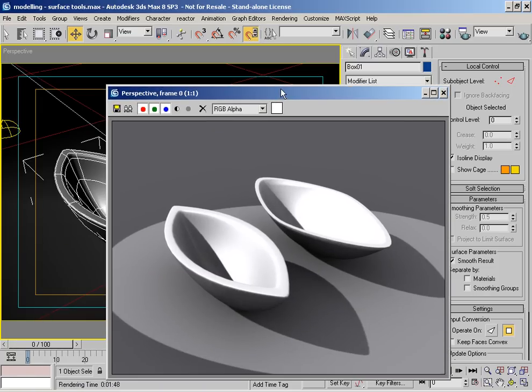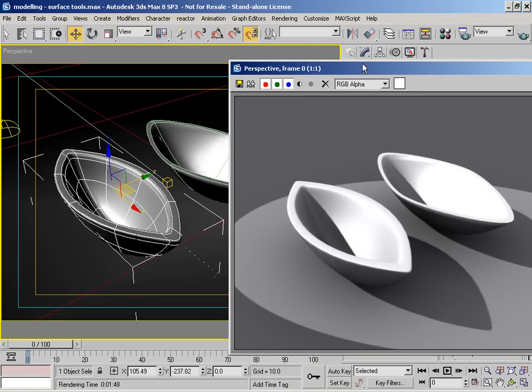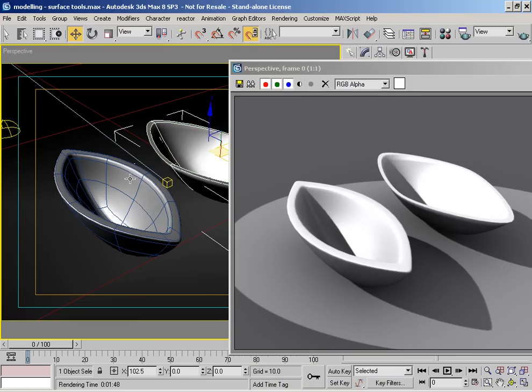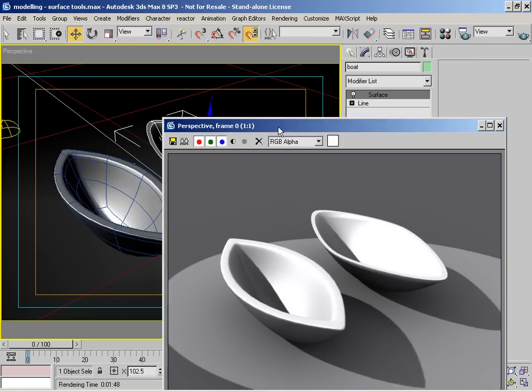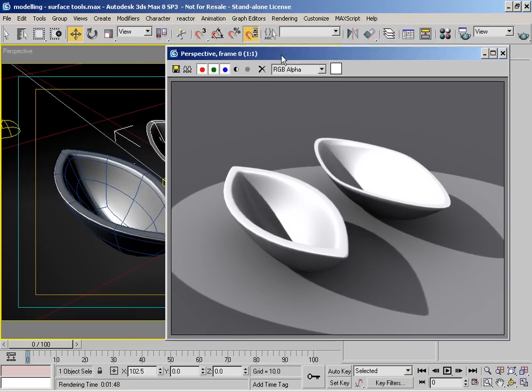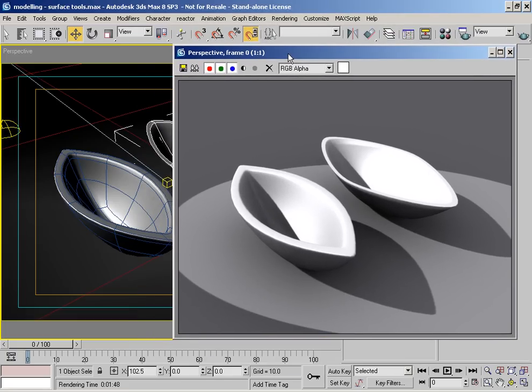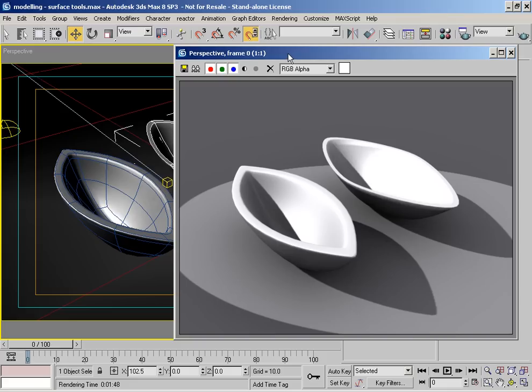So what have we got? We've basically got an issue around here with our patch version. Because obviously Surface Tools uses patches and not geometry. Patches are basically geometry with Bézier handles in essence. You can basically contort them quite easily. It's a skill in itself. Personally, they're normally good to model out organic surfaces, like I say, but I personally tend to collapse them down to an editable poly once I've got the shape I want, and then start refining and polygon pushing using editable poly or edit poly.